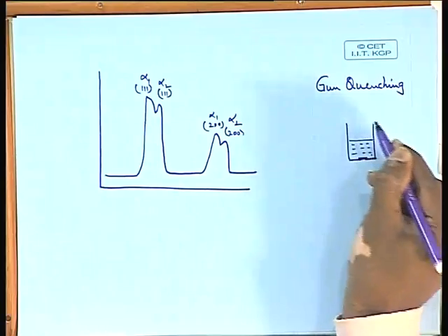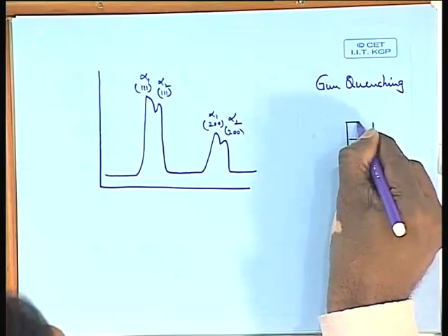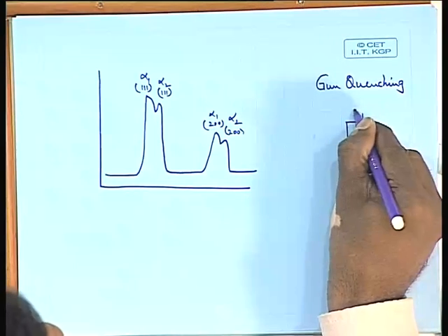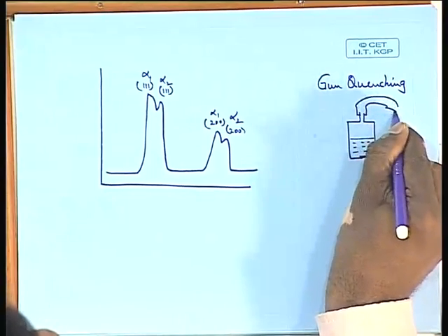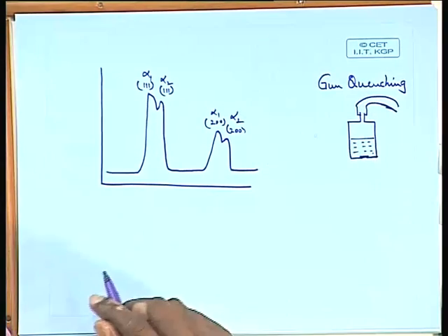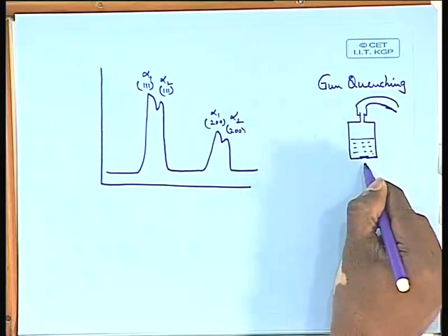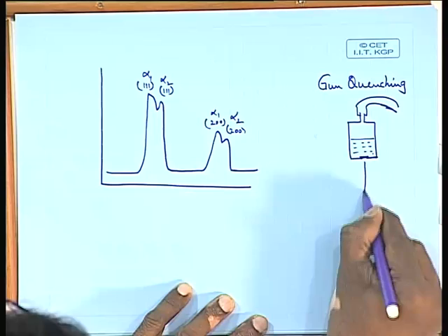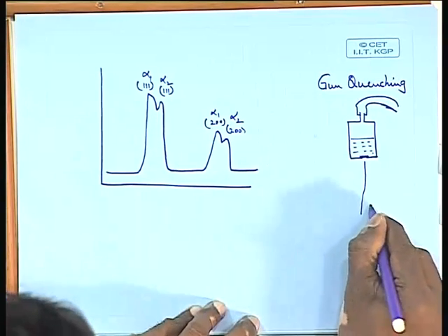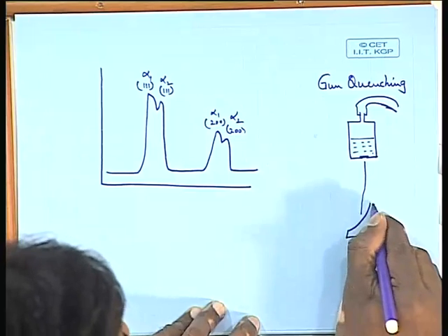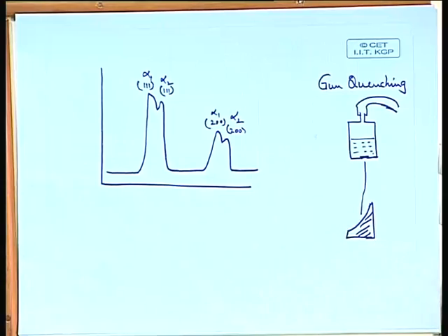Once you think it is molten, you introduce argon into the system and pressurize this liquid with argon. When you do that, the liquid immediately pierces that foil and falls onto a copper block which is kept below.